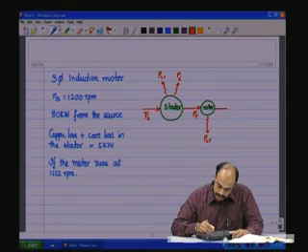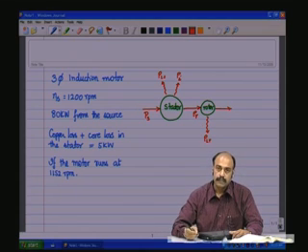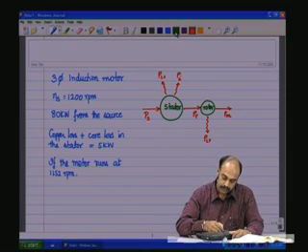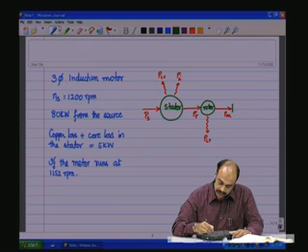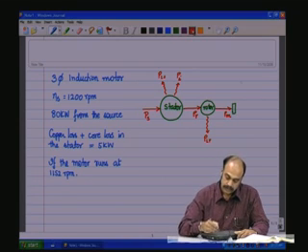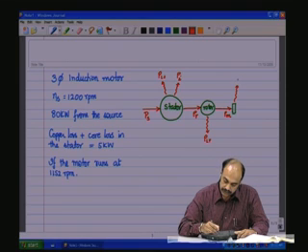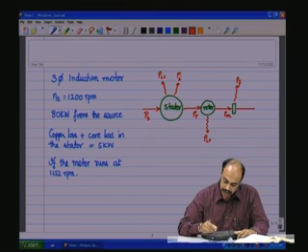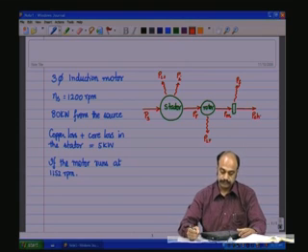The remaining power goes as the mechanical power which is developed. And in the bearings you can have some friction losses, and there is some loss which goes off as friction. So we will say P friction, and the remaining power goes as the shaft power, P shaft.